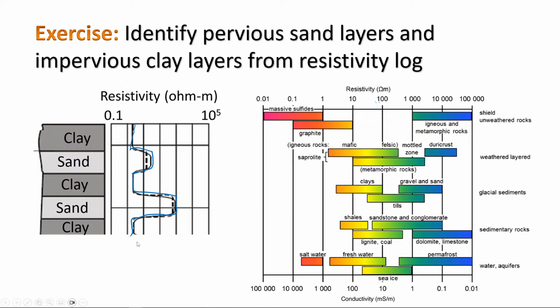If you are doing this to investigate karst, for example, you need to read about karst features and ERT in karst features and get some examples before you go to the field. That's what I did in Ireland. I didn't go to the field and just do this ERT without preparation. I got some sources about ERT and karst and how to interpret, because for each of these rocks the interpretation would be different, and there would be a lot of heuristics and knowledge that you need to gain. Once I gained this knowledge, I was able to interpret the images that we got and say, oh okay, here's maybe a cave, this is maybe a karst conduit, something like this.